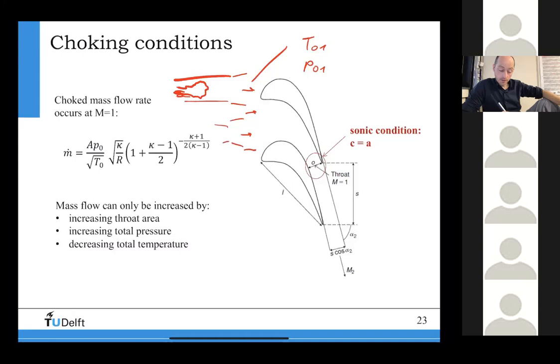Then what happens here is you can easily derive this equation, which is called the flow capacity equation. I show it on the next slide. I will not go through it, but I will leave it in the slide so that you can check how this equation has been derived. It's not difficult. You just need to use basic thermodynamic laws. Basically, you don't need to use gas dynamic knowledge even. You can derive this with thermodynamic equations, and isentropic relations, the definition of Mach number you need to know, for example. And then you can easily derive the mass flow, which is the flow capacity, okay?